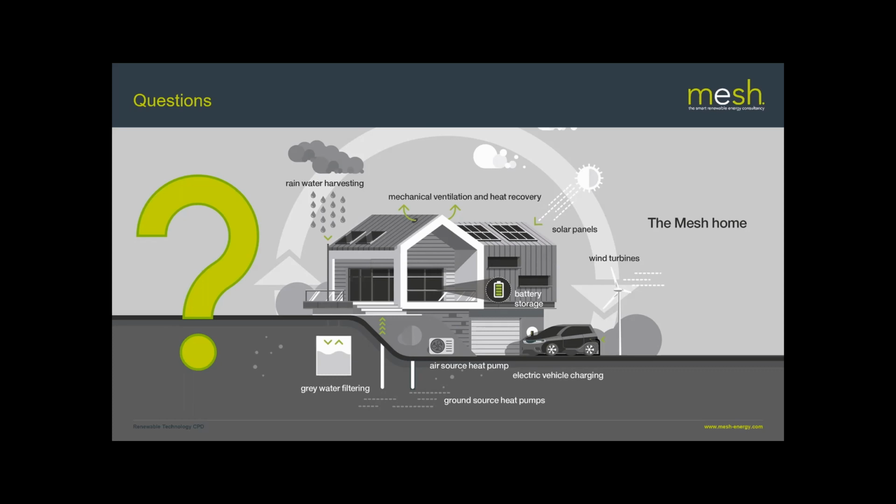So Natasha's asked about air source heat pumps that only do the hot water. There are heat pumps which use exhaust air to prepare hot water, and those can be quite effective. What they tend to do is take heat from the building. If that's part of an MVHR type system, then that can be quite effective. But obviously what you don't want to be doing is putting heat in one part of the building and then extracting it out in another part for no purpose. So you just have to be a little bit careful of them.